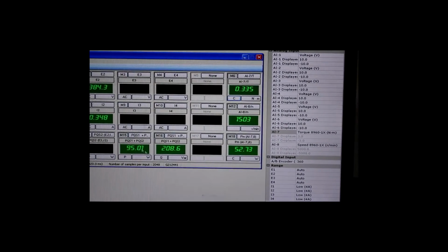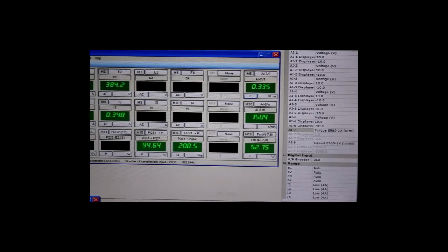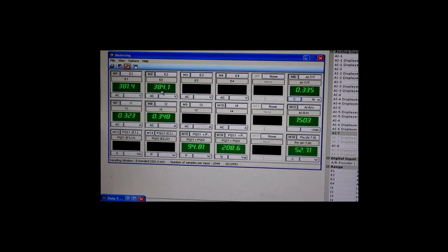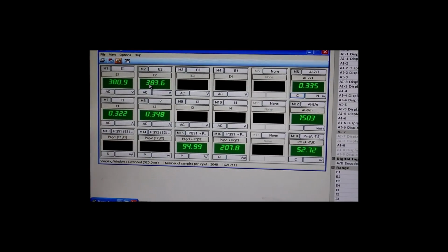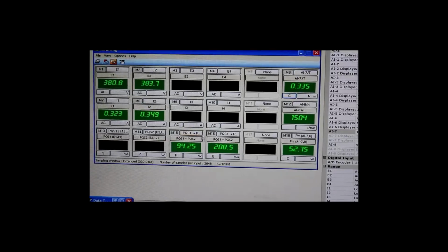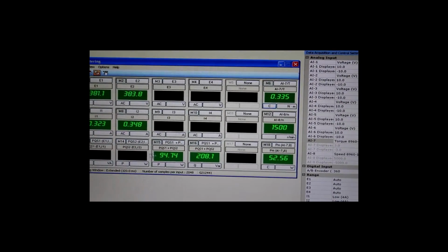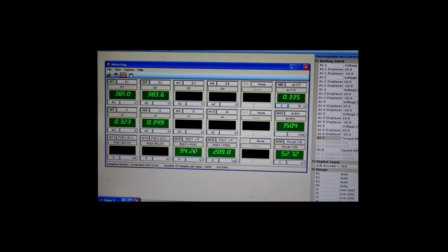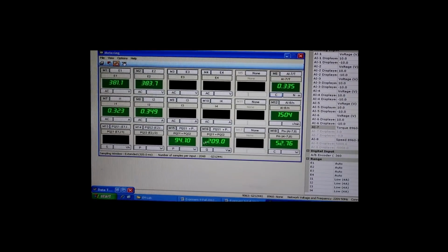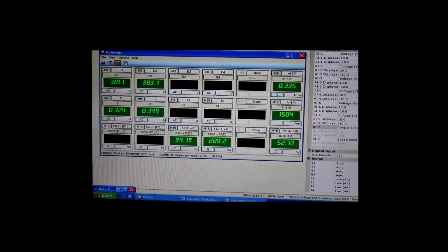Okay. We want to do the power thing, as I said. This is the line voltage. Yeah, this is the line, because the phase voltage is 220 between two phases. Yeah, exactly. Now we need to do something for the metering here, because we want the total Q and the total P. To get that, we have to sum the values of P and Q, P1 and P2.